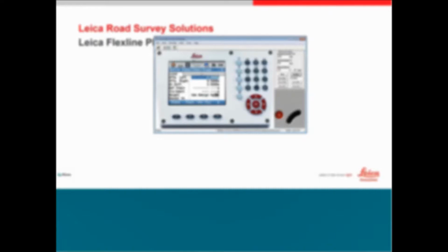Once you have selected them, you can enter the offset value if you want to offset them. You can have different offsets on the left and on the right, for example 8 meters on the right, 5 meters on the left, and then the height difference. For each layer of the road there will be height differences, like I showed you on the typical road component.